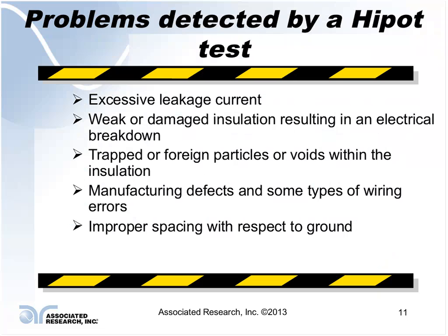Let's face it, if the leakage current gets too high, this can create a shock hazard, especially if somebody defeats a safety feature in your product. If your product is meant to have a grounded metal enclosure with a ground circuit, a Class 1 product, and somebody defeats that ground circuit, if the leakage current from the primary circuit to the enclosure is too high, it's going to create a shock hazard to the individual as soon as they come in contact with it.